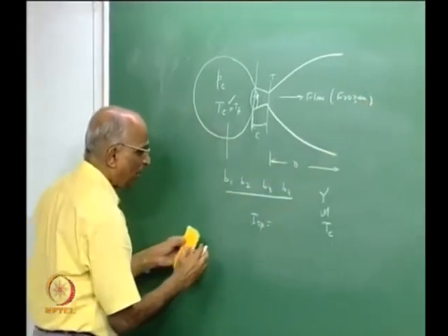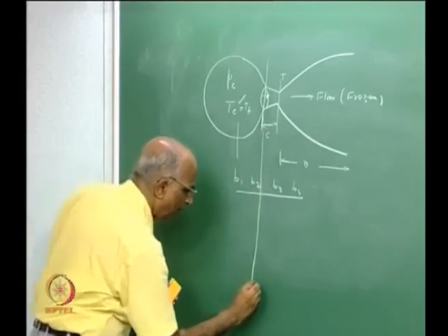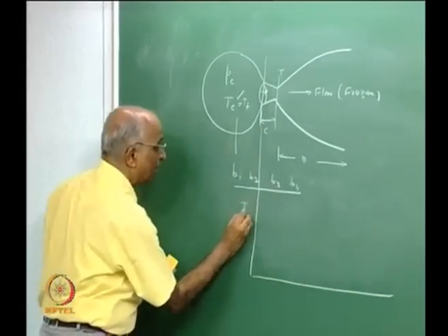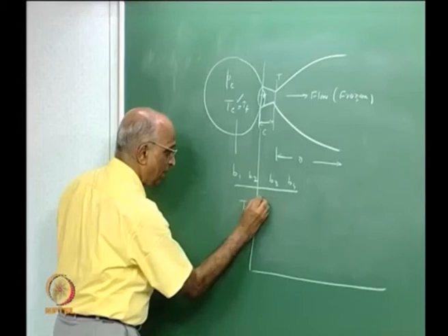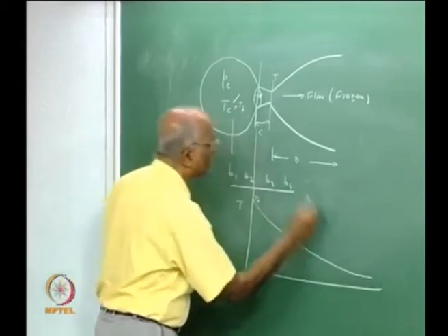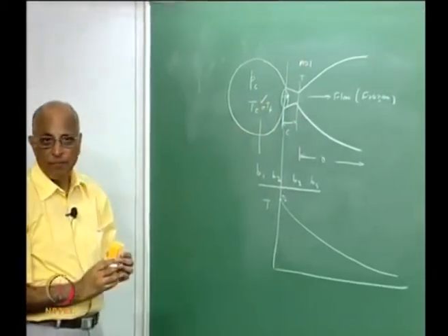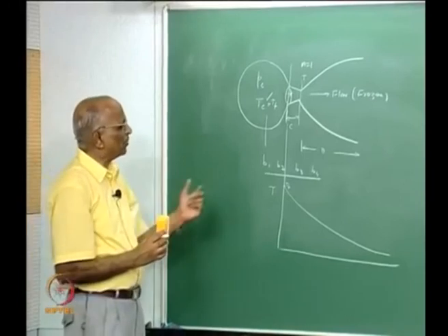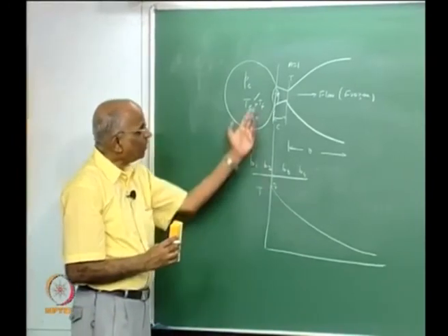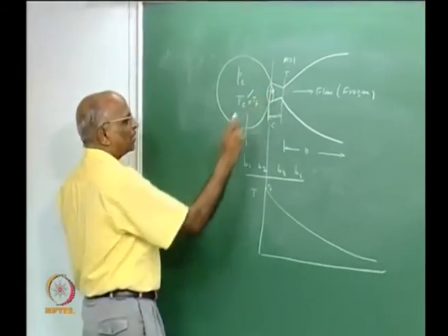And what did we determine? Let's plot it. We determined the variation of, let's say, temperature from the adiabatic flame temperature which we have just calculated, and as it goes on, we have the throat at Mach equal to 1, right. But now there is some subtle difference. As the flow takes place, temperature drops, therefore let us take a section here.